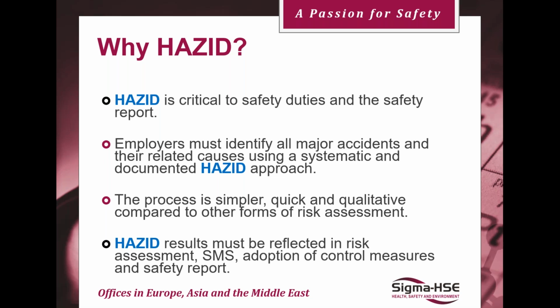So why HAZID? In the UK, we have a safety report to produce if you are a COMAH site, and a top tier COMAH site as well. And that's one set of, essentially it's the process safety regulations in the UK. And the HAZID is a very good way of demonstrating that you are undertaking a fit and appropriate risk assessment.